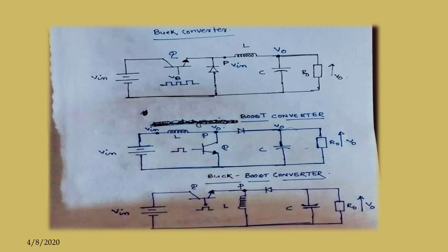So in the total period, that is T on and T off, the volt second applied to this inductor is 0 in steady state, right?